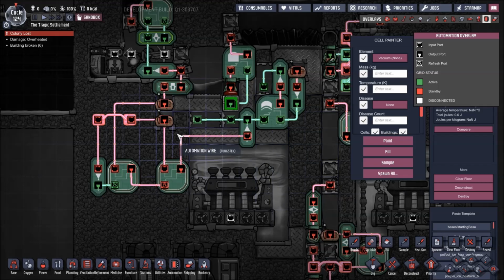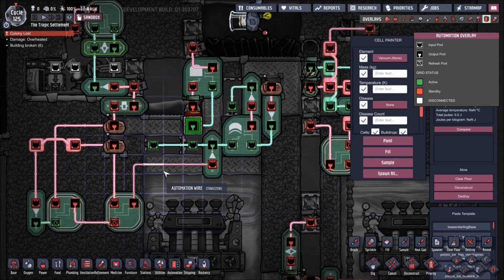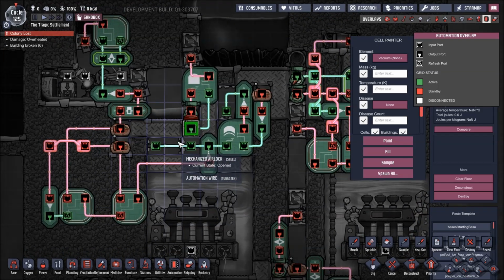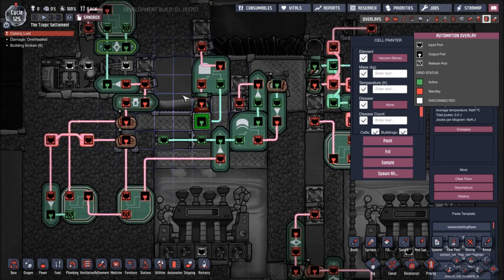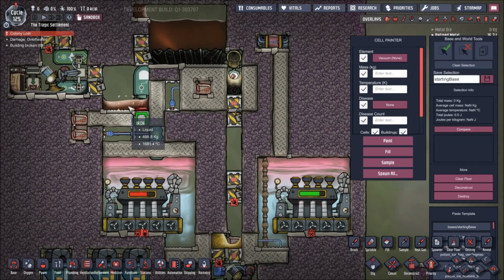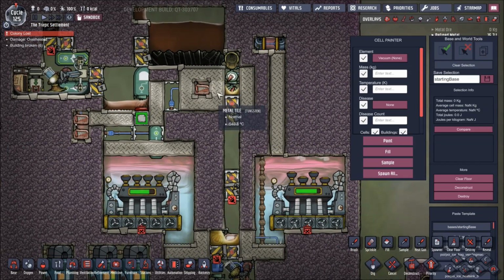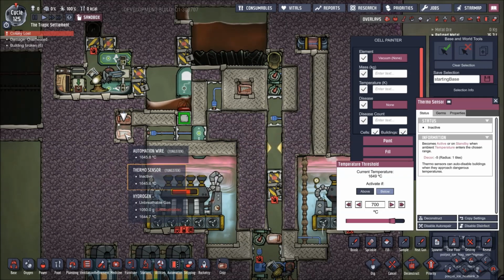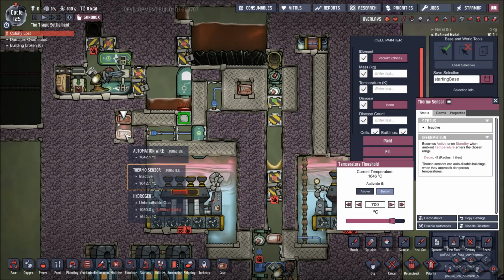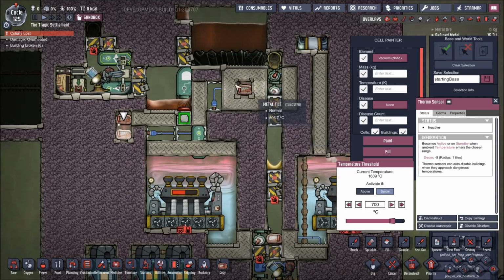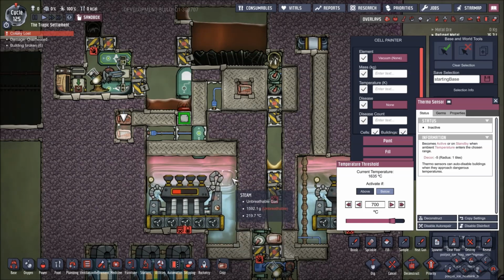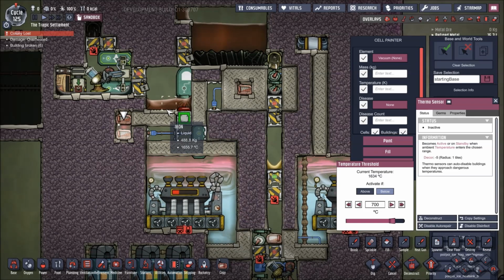The roughest, tumblest part of the automation, this part I had trouble wrapping my brain around, how to get this system to actually work, because let me explain what needs to happen. And I might be kind of talking too much, but I like to explain these things. When this iron is cooled down to a point where it's no longer transferring enough heat into the oil, which I have set to 700 degrees, that's what this second thermal sensor is for. This sensor is essentially the threshold at which we stop transferring heat over to the oil and start transferring it down into the turbine room here to cool the iron down a little bit quicker.